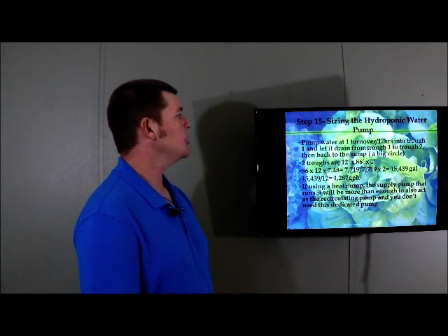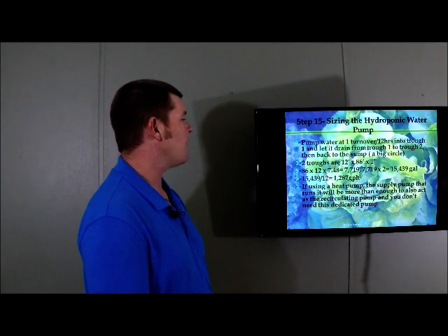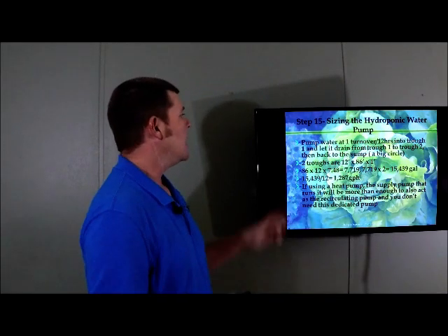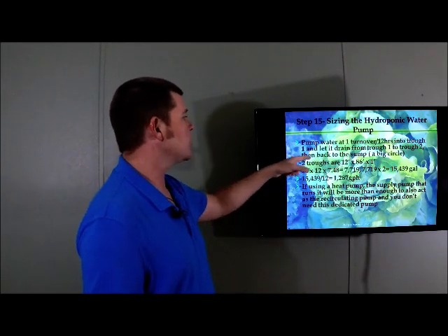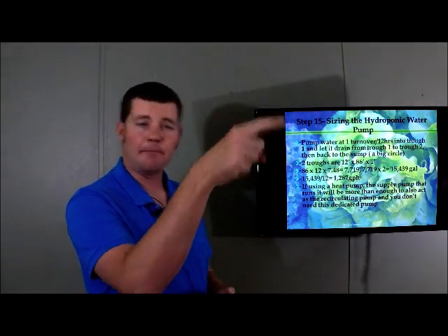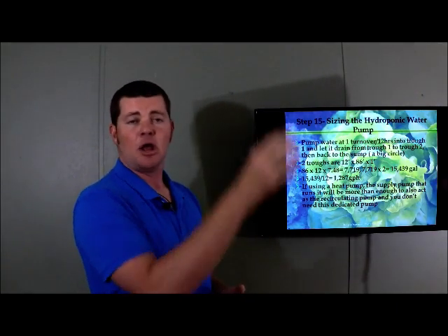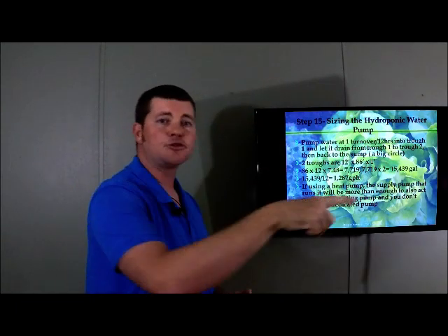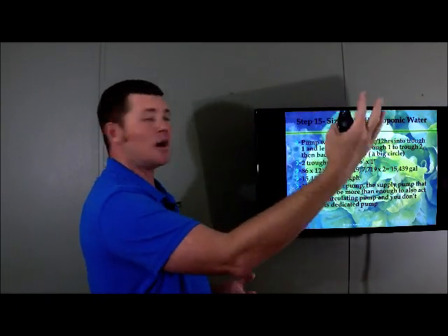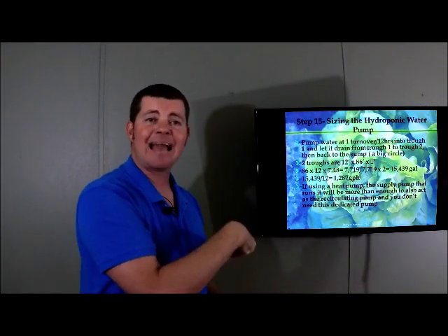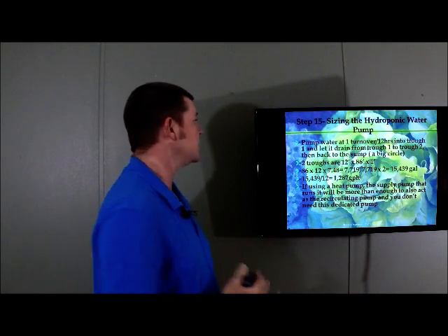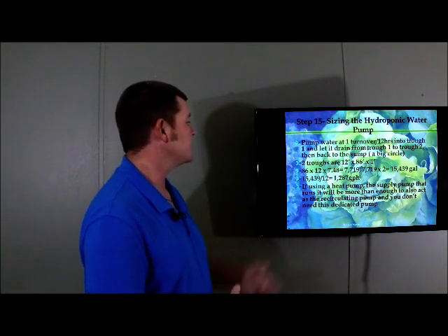Pump water at one turnover every 12 hours into trough 1. So we're pulling from the sump, pumping into trough 1, and letting it drain from trough 1 to trough 2. At the far end, we'll have them plumbed together underground. The pipe will go as trough 1 rises, water will drain into trough 2. Trough 2 will drain back into the sump. So this causes a circle. It causes the water to circulate between these two large troughs.